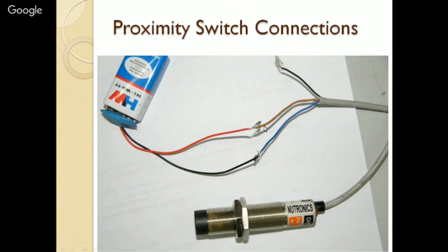Accordingly here, to the brown one, the red wire of the snap is attached, and to the blue one, the black wire is attached. So this is the ground basically. So we have a 9-volt standard battery which is attached to these two. Now, the output can be measured across this black and this blue, right?